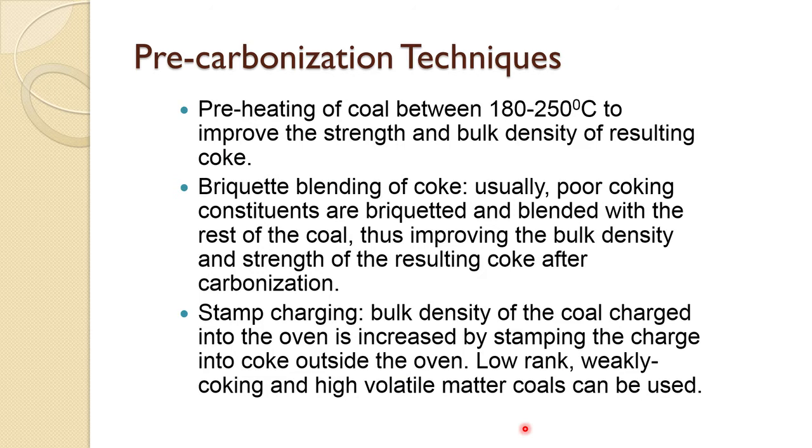Now, pre-carbonization techniques, such as preheating. Before we do the coking, there are some other things one can do, depending on whether you do not have a very good quality coal. You can increase the efficiency of the coking or make a good quality coke using these techniques.